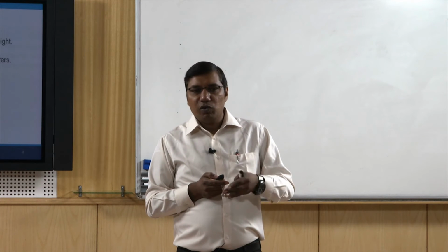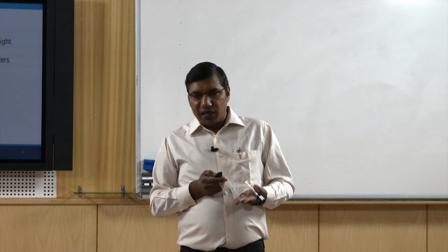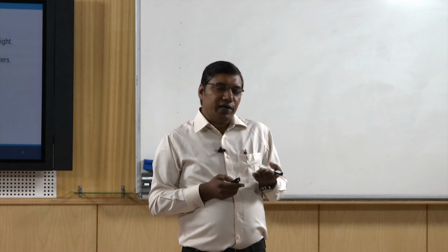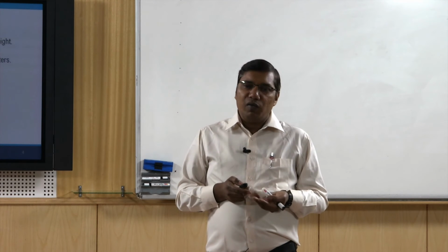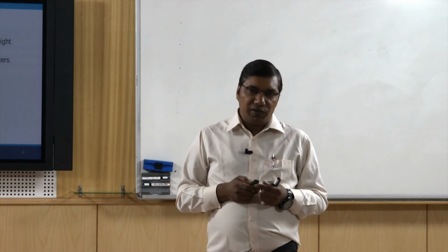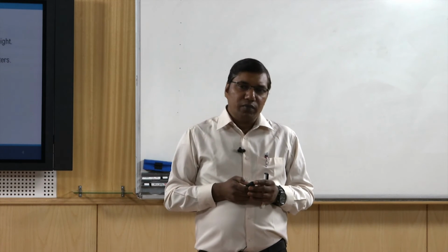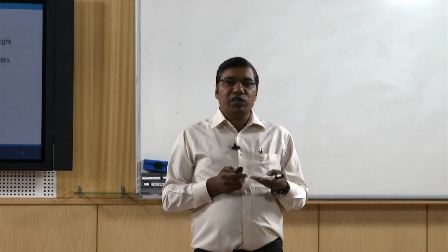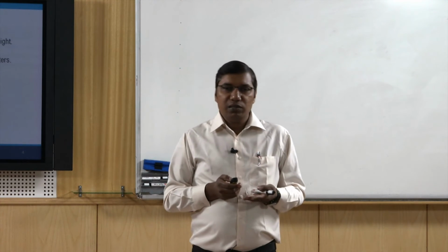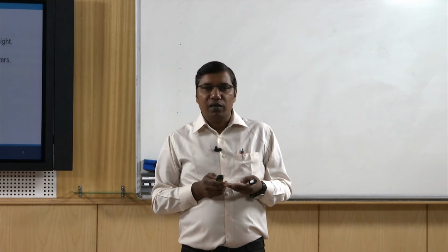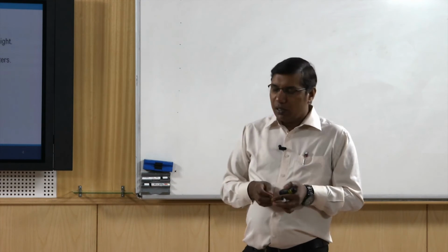So if our road profile gives some excitation from the support as y sin omega t, omega is the excitation frequency, and our system has some mass and stiffness, so it has the natural frequency omega n equal to root k by m. When omega is equal to omega n, this is the critical condition, and the speed that we will get under this condition will be the critical speed. So let's solve this problem.